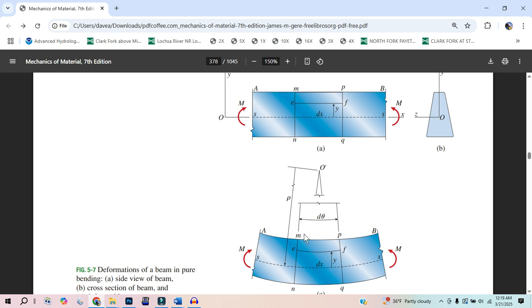That's the cool thing, as long as you're within that linear range and you didn't crunch the top end more than 0.002. Every meter, this crunching in didn't become 998 millimeters. If you didn't do any of that, then every molecule goes back to the original position.